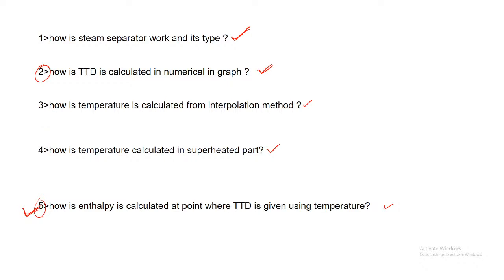So these things would be given, and if not given, then we would have been given certain other things, like the amount of heat given in the boiler. From that amount of heat given, we can calculate the temperature in the superheat part. Since superheat is simple, we know the enthalpy at the dry saturated vapor, and then we wanted a certain enthalpy. So we know that H is the enthalpy at the exit of the superheater. So H minus H saturation is the amount of superheat.